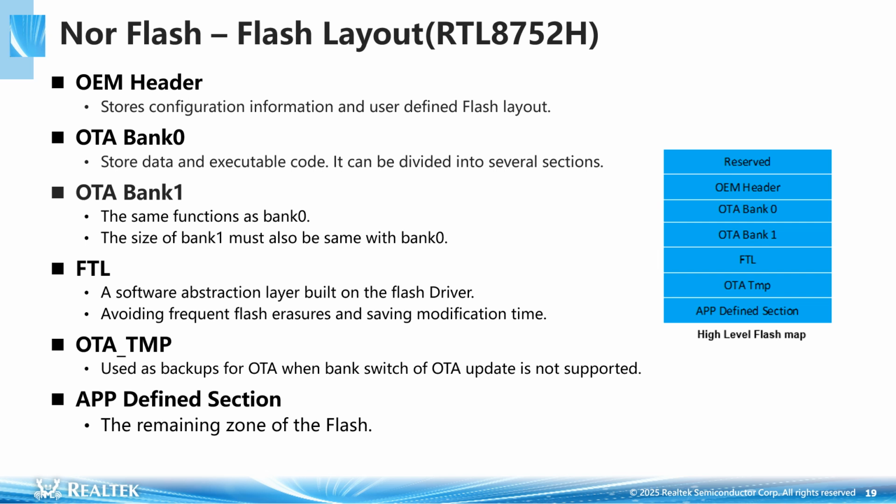FTL is a software abstraction layer on flash that extends lifespan and improves storage efficiency by reducing frequent flash erase operations. When bank switching is not supported, the OTA temp area is used for OTA upgrades. Developers can freely utilize the remaining area according to specific application needs.